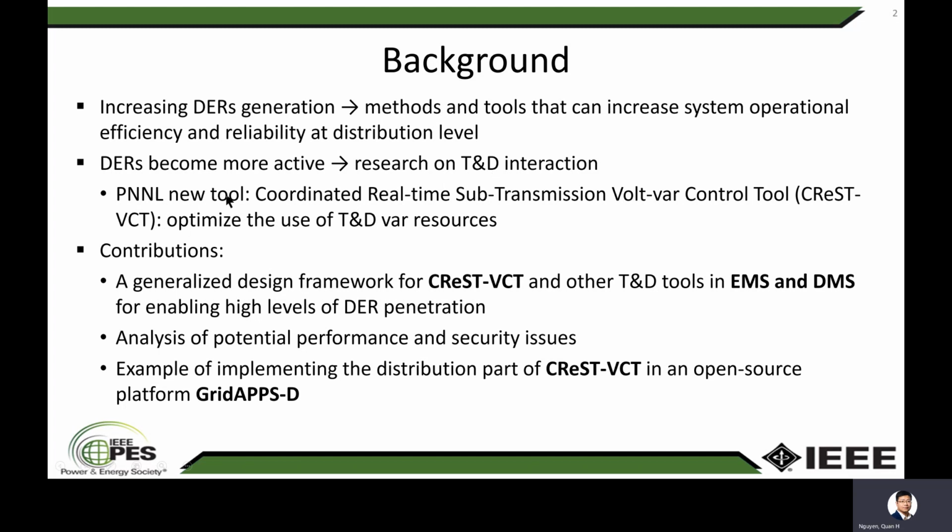Recently, PNNL developed a new tool, which is the Coordinated Real-Time Subtransmission Volt-VAR Control Tool, or CReST-VCT. It is an optimal operational tool that optimizes the use of all reactive power resources at subtransmission and distribution levels. In this work, we develop a generalized design framework for CReST-VCT and potentially other T&D tools in EMS and DMS to enable high DER penetration.